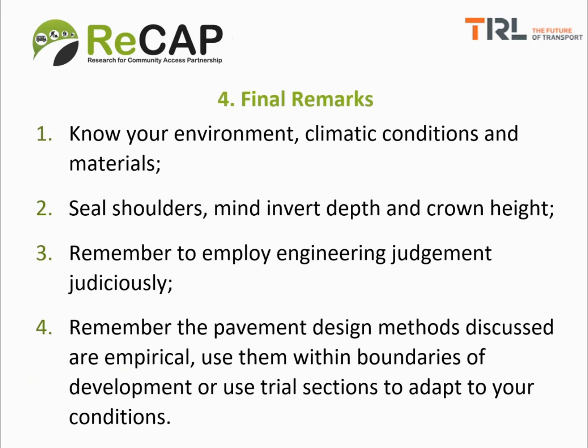The second remark is in regards to drainage. Drainage is very important to the performance of low volume roads. And we emphasize the point that you should always endeavor to use sealed shoulders on your roads. That is if you're building sealed roads, but for gravel roads, of course, you cannot seal the shoulders. But you should mind the invert depth for both gravel and sealed roads and the crown height for both gravel and sealed roads.